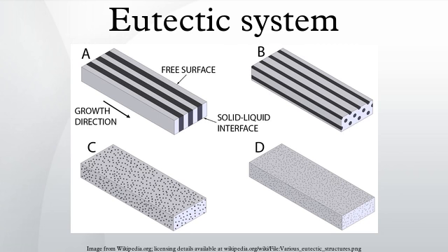Eutectic reaction. The eutectic reaction is defined as follows. This type of reaction is an invariant reaction, because it is in thermal equilibrium. Another way to define this is the Gibbs free energy equals 0. Tangibly, this means the liquid and two solid solutions all coexist at the same time and are in chemical equilibrium. There is also a thermal arrest for the duration of the change of phase, during which the temperature of the system does not change. The resulting solid macrostructure from a eutectic reaction depends on a few factors.